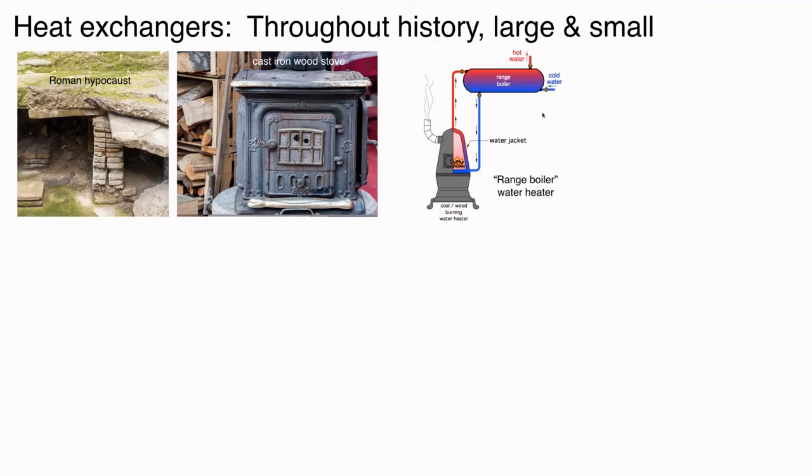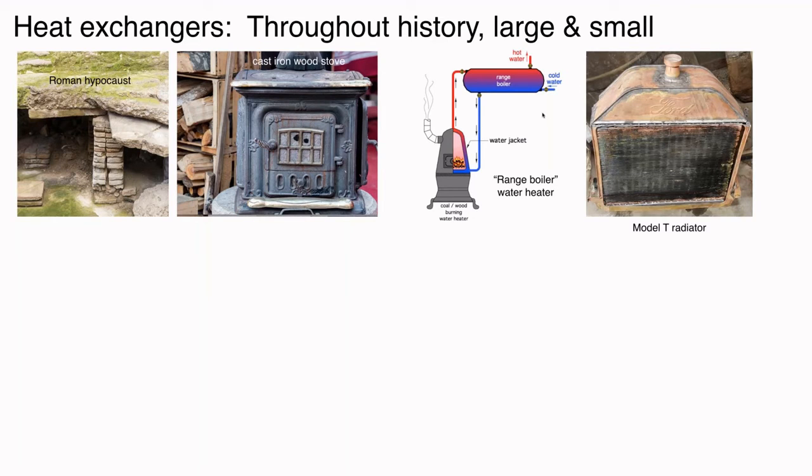I'm not sure where that term came from, but basically it's just a tank. These used to be just galvanized steel tanks. You can see it's installed above the wood burner, and there was no circulator because there was no electricity at this point. This relied strictly on natural convection heat transfer to take the heat from the flue gases, transfer it through that metal wall of the water jacket, and then ultimately put it up into that tank.